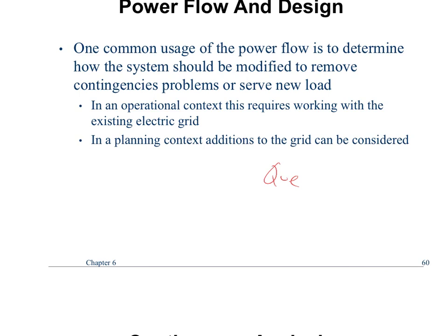And when you're ready to turn on customers, you need to know approximately how much load you're going to pick up. And then you have to tell the generators to be up and running and ready to go, to have a big change in their power demand. So sometimes they'll try to stagger it. So they'll turn on a transmission line, and then they might have turned off a bunch of distribution circuits, and then they'll turn them on one at a time to sort of limit that. But one of the challenges with figuring that out is something that's called cold load pickup.